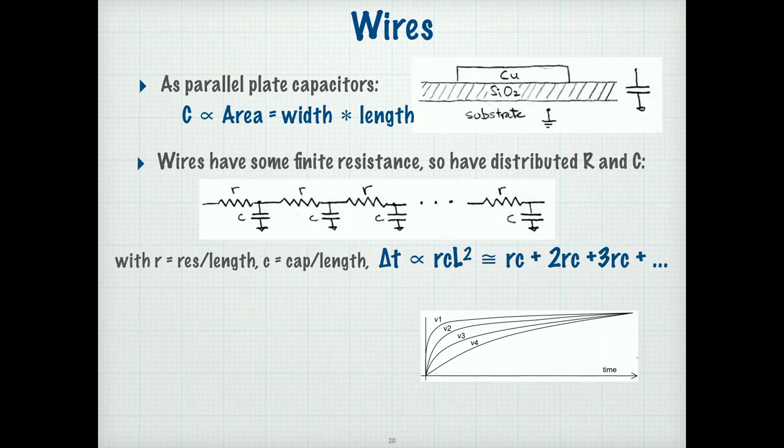So this is kind of the R per unit length. Consider each piece here as a unit length piece. So we have R per unit length and C per unit length. Right? Now, think about the dynamics of this then. If you put a voltage source here and try to change the voltage of that side, we're sending a signal along the wire. That means we're going to change the voltage here by, let's say, connecting this up to VDD. And we'd like to get that 1 all the way to this side. How is that going to go?